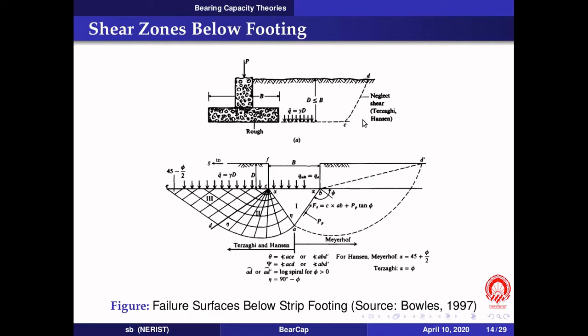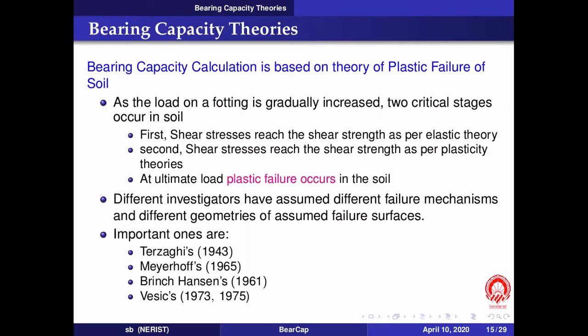These are as far as the calculation of bearing capacity from the very preliminary analysis, but as engineers we never do this kind of analysis. We use whatever solutions are given by these researchers, Terzaghi, Meyerhof, Hansen, Vesic, etc., while calculating the ultimate or net ultimate bearing capacity. And in a moment from now we will see how to do that.